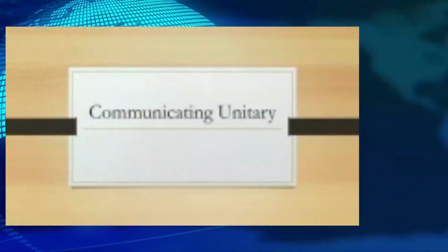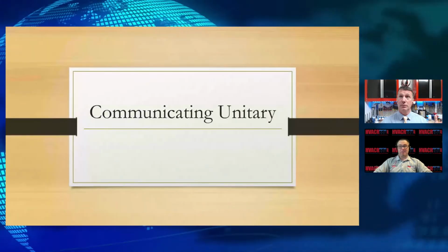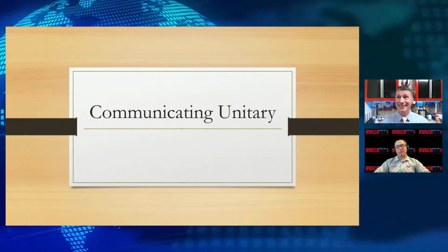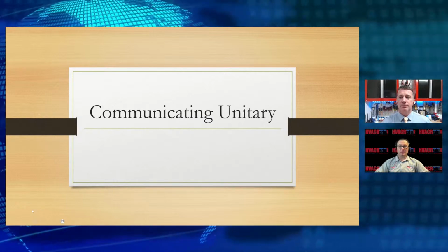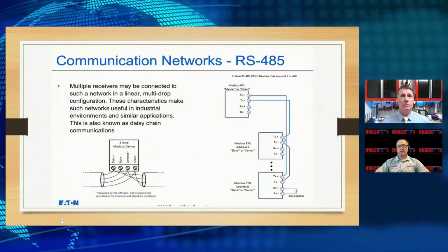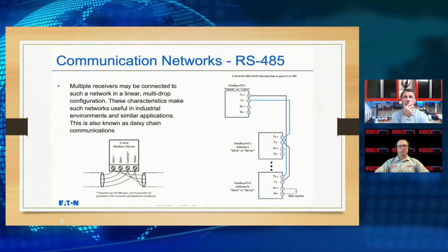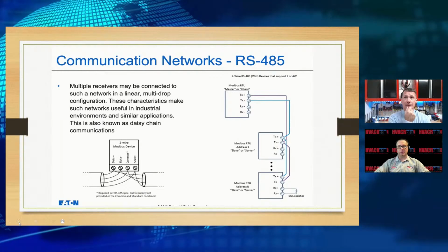So, Todd, you spent a lot of time on the BAS side of things, building automation, and you guys have a great course over at HVACR EDU. So a couple of these slides are in reference to intro stuff into BAS, because BAS and our unitary communicating really are very similar. Six of one, half a dozen of the other, right? I mean, they're very similar in the way they communicate. It's going to be a DC voltage, usually 5-volt DC, and very similar to pulse width modulation. We may have heard that in the industry, right?